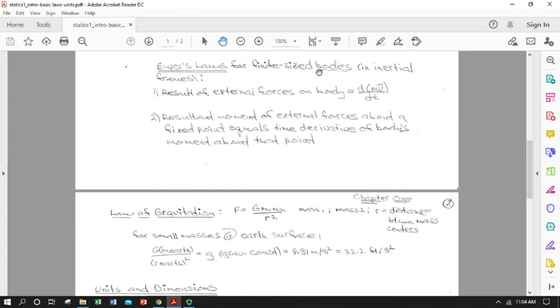So if you've got a finite body, like a beam or a truss or a gear with teeth, and you put it into an inertial reference frame, and in the case of a machine, it might be a single point where it's tied down or fixed to a floor, or it could be one of the axes that's rotating, anything like that. You can write Newton's laws a little bit different way. Instead of saying the sum of the forces is equal to the body's mass times the acceleration of its center of mass, we can add up momentum. That's the other way of writing Newton's second law.